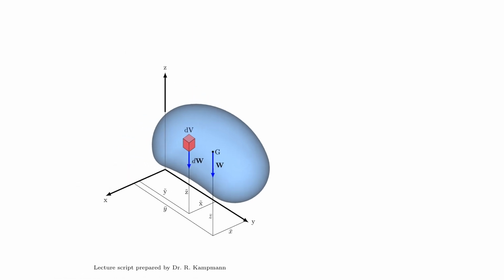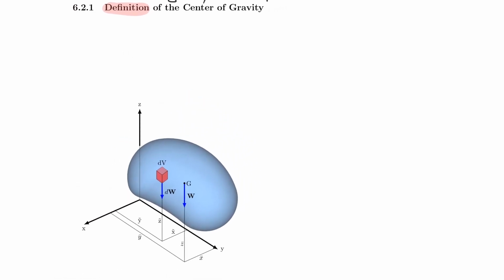So now the way the center of gravity is defined is that whatever point in space you choose, let's say you choose the origin of the coordinate system, there is a weight times a lever arm. In the x direction, it would be W times x bar, and that would create the equivalent moment as each individual particle times its distance.